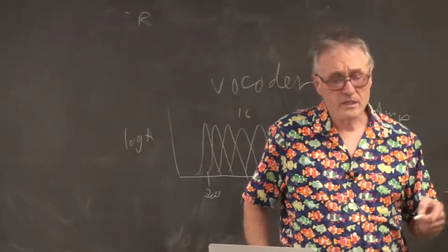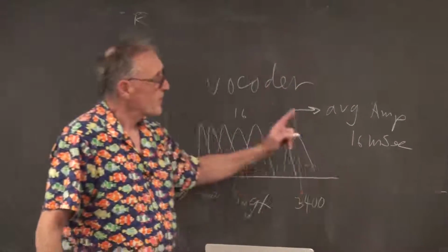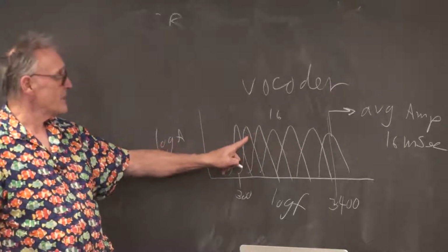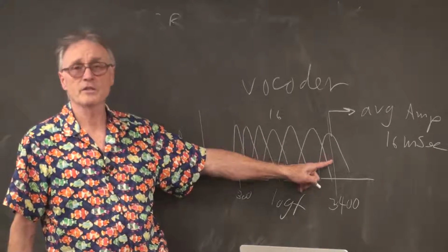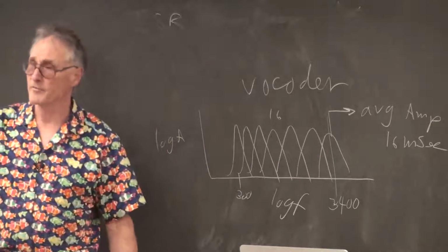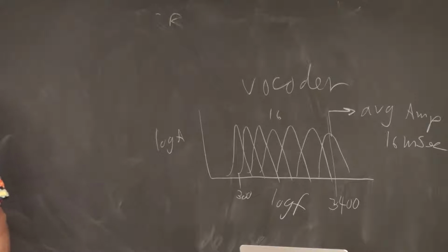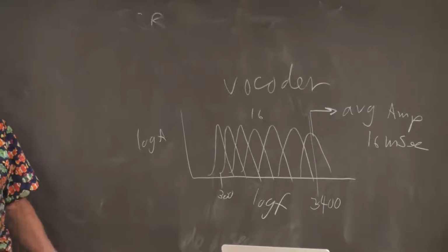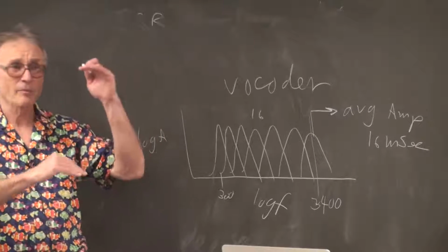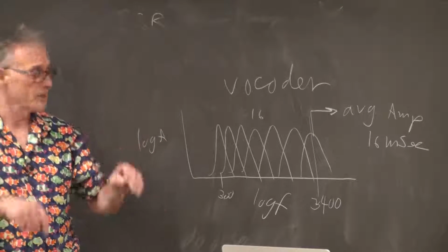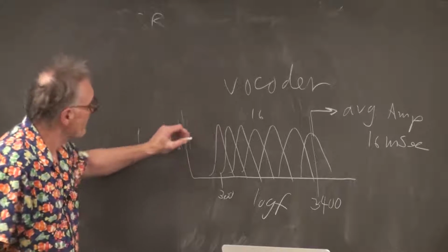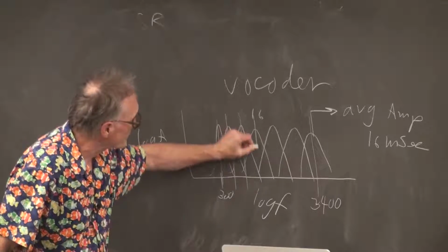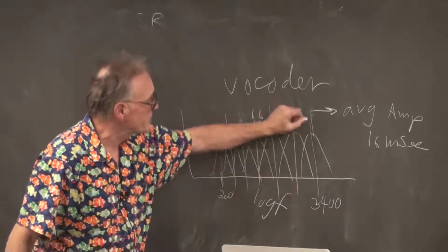So what we're listening to there now is you take every 16 milliseconds, you take 16 coefficients, you put them in RAM or in flash. On playback, for a 16 millisecond time interval, you take the 16 amplitudes that you have recorded, you synthesize a sine wave at the middle frequency of each of these bands, only a pure sine wave at the middle frequency of each of these bands.